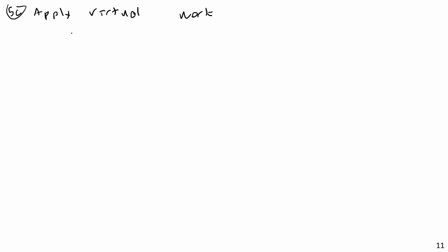And so, since all members have the same AE, maybe I can show it like this. Initially, we have the formula 1 times delta is equal to the summation of FV times FL over AE.